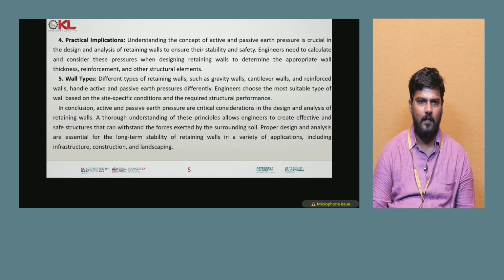And coming to what are the practical implications? Understanding the concept of active and passive earth pressure is crucial in the design and analysis of retaining walls to ensure their stability and safety. Engineers need to calculate and consider these pressures when designing retaining walls to determine the appropriate wall thickness, reinforcement, and other structural elements. Different types of retaining walls such as gravity walls, cantilever walls, and reinforced walls handle active and passive earth pressures differently.